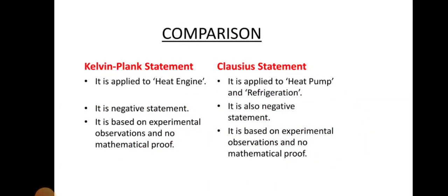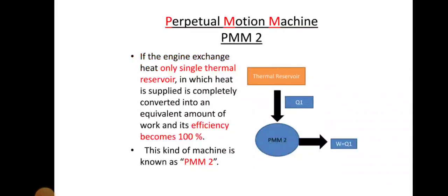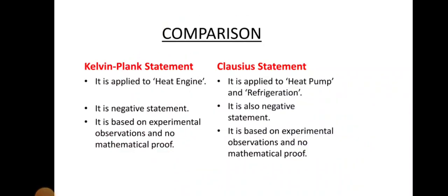Now we can compare the Kelvin-Planck statement and the Clausius statement. The Kelvin-Planck statement is applied to heat engines. The Clausius statement is applied to heat pumps and refrigerators. The Kelvin-Planck statement is a negative statement. The Clausius statement is also a negative statement. The Kelvin statement is based on experimental observation and has no mathematical proof. These are the comparisons of the Kelvin-Planck statement and the Clausius statement.